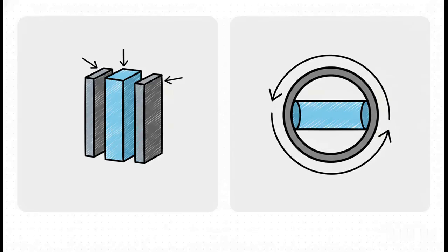And the reason for going 3D all comes down to one word: control. The FinFET design wrapped the gate around the channel on 3 sides, which gave it a much better grip, stopping those leaks. But the GAA-FET, well, that's the ultimate version. The gate completely surrounds the channel on all sides. This gives it almost perfect electrostatic control, which is what allows us to keep shrinking transistors without them failing.